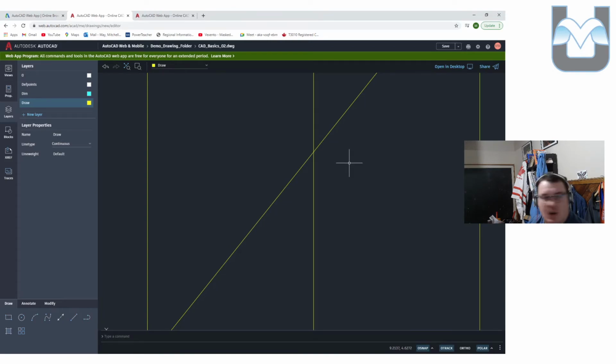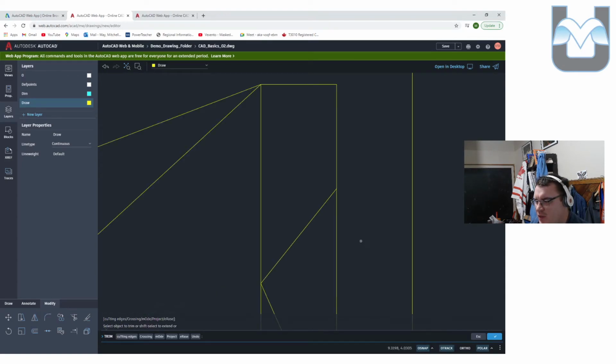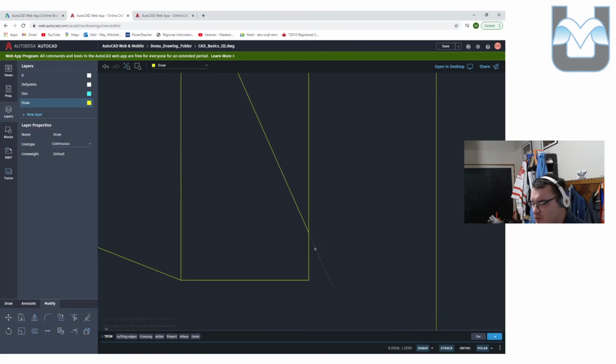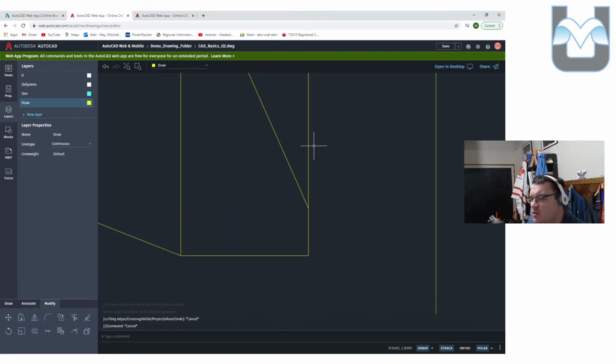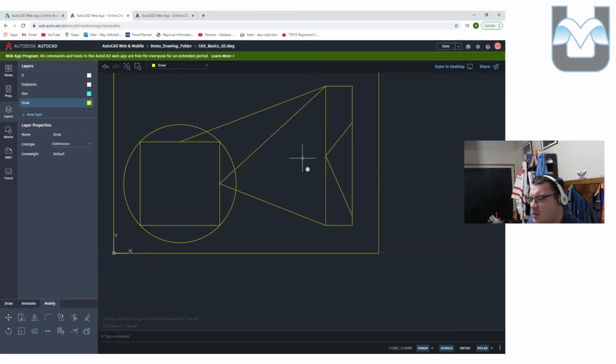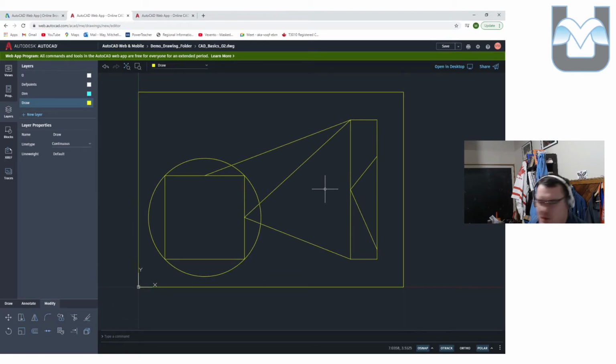So to cut something off of these lines, I very simply go trim. Okay, this is also under your modify menu. There's a pair of scissors down here in the bottom left. Okay, we go trim, and under trim, I'm able to just click lines and cut them off, and they're actually going to split themselves according to where something has gone through the middle of them. So there's the trim, and that means that I've got those lines ready, easy to modify, easy to address, easy to put an angle on.